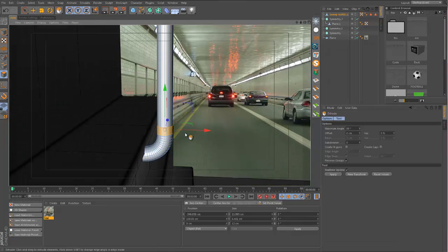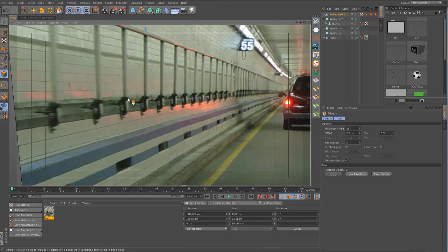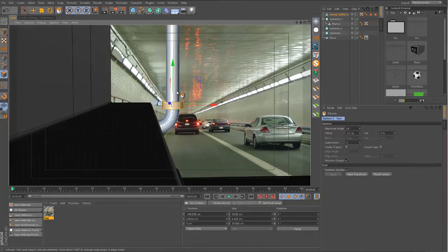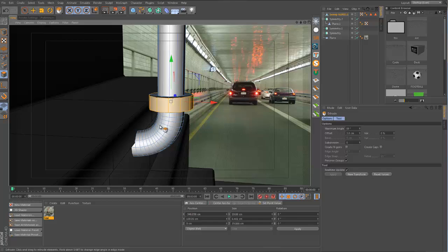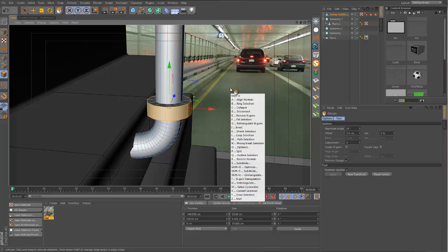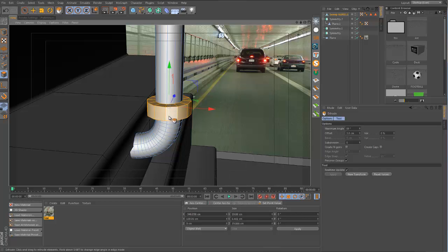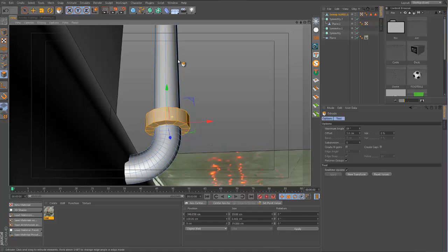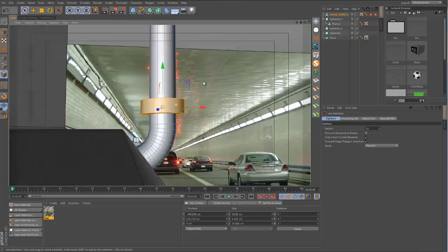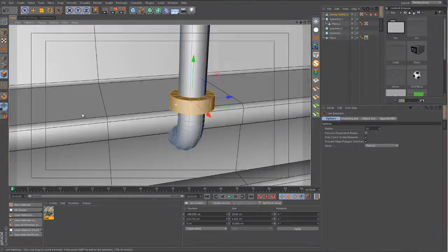I can extrude it out. It looks to me like there's something gripping it around in a circle. So that is that little section there, and I'm going to expand my selection to select these two here. If I press U followed by Y, my selection will be expanded, basically following the same loop. If I did that again, this loop will be selected and this one will be selected. When I move this whole thing up, to about here looks pretty good.